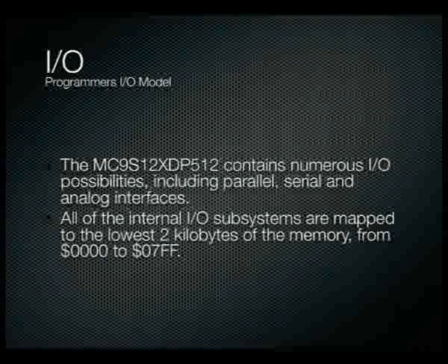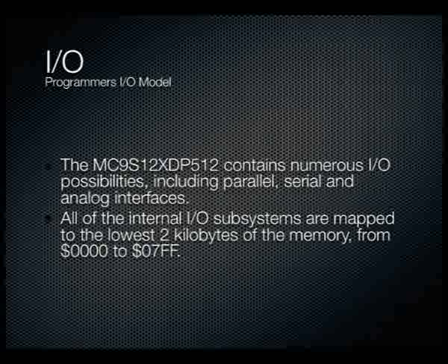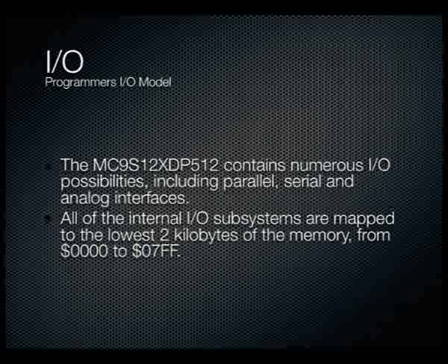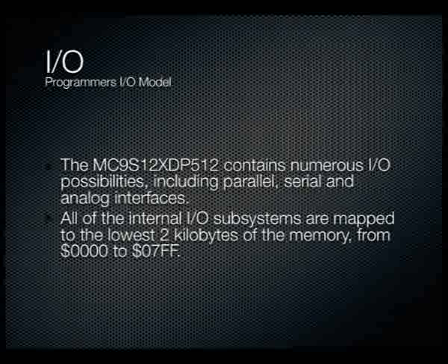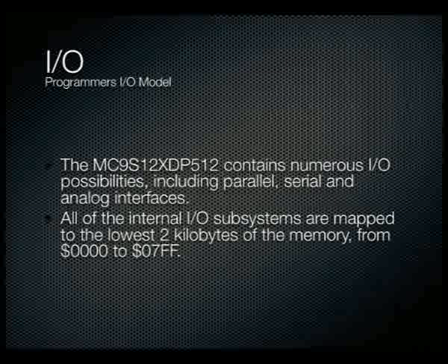Okay, so programmer's I/O model. When I talk about all these various subsystems, I will talk about their programming I/O model, because the programmer's I/O model is effectively your interaction as a programmer with that particular subsystem. Our interaction with these subsystems is all via a series of registers, memory mapped registers for a particular subsystem.